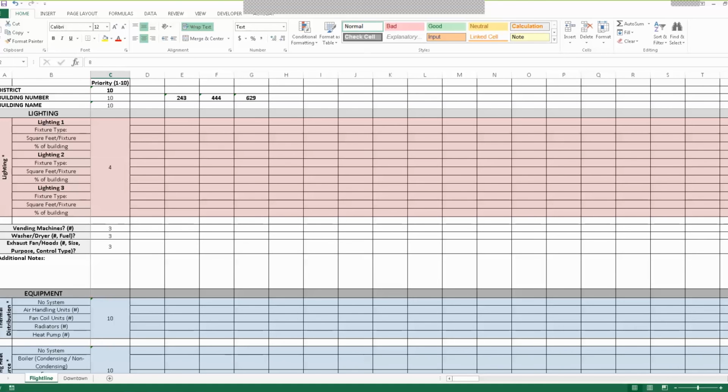And so if you can do a sampling, count your ceiling tiles, whatever, get your area, count your fixtures. There's a lot of standard watts per fixture type. You can rough that in pretty quick. I think it's more in that priority 4, priority 5, because in many cases, if it's a little bit newer building, this is probably going to be closer to the default anyway. The real benefit in lighting comes when you go in and do a real detailed lighting design going forward, where you start really looking at the indirect, direct, task lighting, and cutting down.